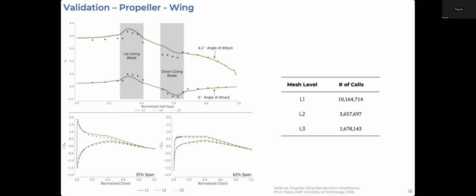We'll also do a propeller power optimization where we'll optimize simply the orange quantities here, where we'll minimize propeller power with respect to propeller design variables of twist, chord, rotation rate. And we'll have some design variables such as the propeller chord concavity and the chord bounds, which are necessary to make sure the design is reasonable and doesn't break the physical model.